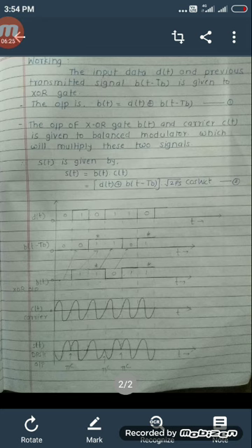Okay, so according to this, we have considered the first bit of d(t) as 0, and as the initial condition, the first bit of b(t-Tb) is 0, so the output of the XOR gate, that is b(t), will be 0. Then that output of the XOR gate b(t), the first bit 0, is considered as the previous transmitted bit for the next bit of d(t). Meaning if you consider the next bit of d(t), that is 1, the previous transmitted bit is 0, carried forward from b(t).